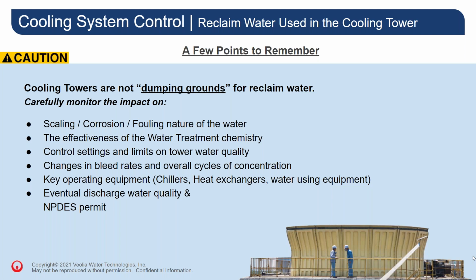Also, by nature, condensate is low in hardness, alkalinity, and dissolved solids. So it's going to be very much less buffered, could contribute to a lower pH, and typically create a more corrosive makeup water quality than possibly beforehand, where your water may have more of a scaling tendency. So while this near pure water quality can have benefits in allowing for greater cycles of concentration in your cooling system and reduce the need for freshwater makeup, it can also be threatening if its quality is not understood and the chemical treatment program and system operational parameters are not adjusted accordingly.